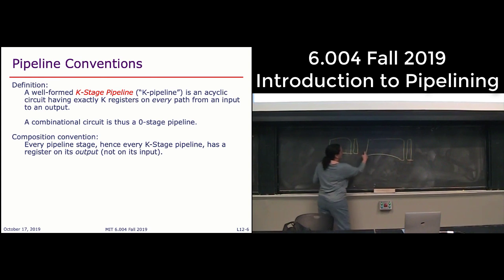And so I don't add to the clock period of any register-to-register path here because it's already covering the same time that I was covering in the clock period of the individual component, okay?